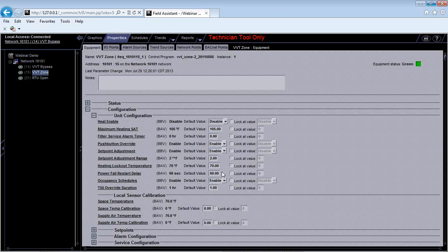Okay, when you have one of the digital display sensors that we saw before, those RNet sensors, you can actually adjust this value on that sensor locally. You can go from 0 to 4 hours, I believe, every 30-minute increments. So you can actually put in that duration. But if you just have a button on there, you can set up however long you want that to be. Something you usually want to confirm with your customer.